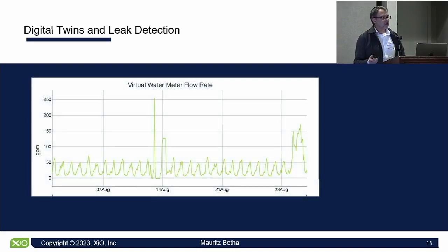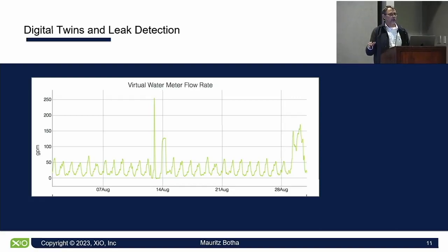Here's another use of digital twins, and that is for leak detection. In this example that we use, we focus on smaller utilities. They typically have a tank, and we monitor the tank level, and then from that calculate the usage. But it's a little bit complicated because, as you pump water at the top, you get sloshing and then you get all kinds of bad measurements.